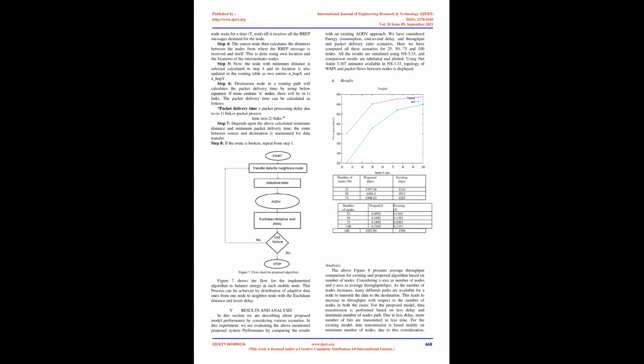This uses the physical layer channel information to be made available at MAC layer. The receiver calculates the signal strength of the transmission channel using channel model simulation at the physical layer. The parameter used for channel estimation at the receiver is termed as power indication PR, which is calculated based on EQ. 2. Receiver estimates the signal strength.